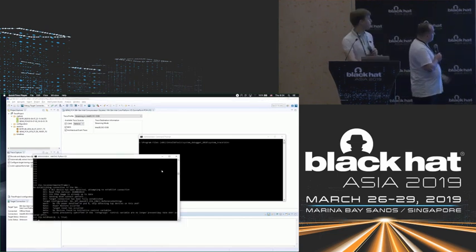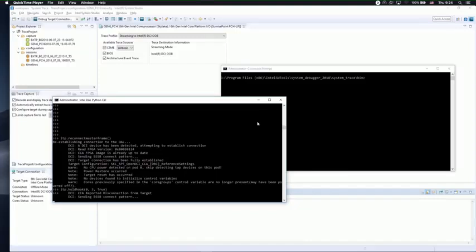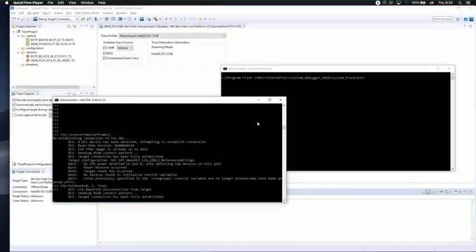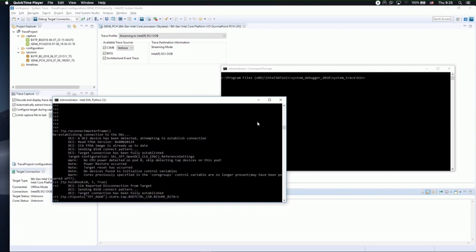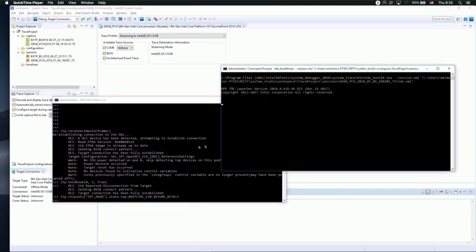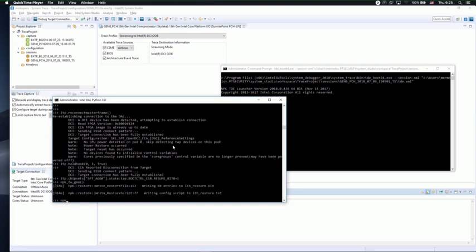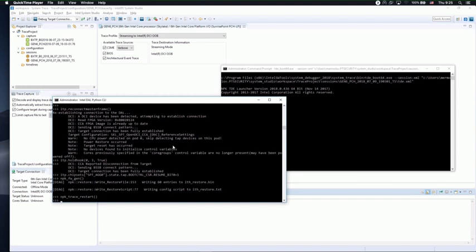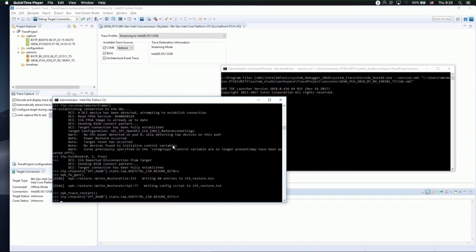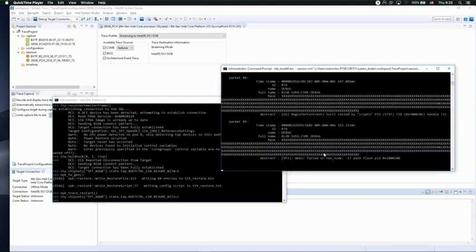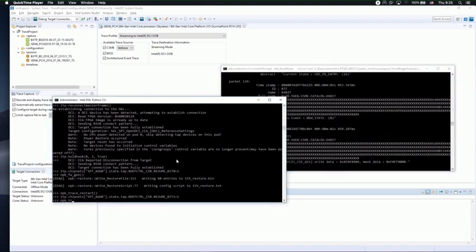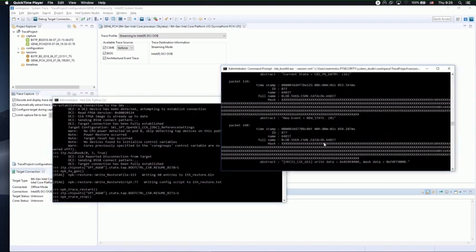Here we're using the mentioned utilities, first for TraceHub IP and second for Trace Decode Engine. We freeze the starting of the ME core. We instruct to reset the ME core, so it traces the startup process. You can see messages from ME.